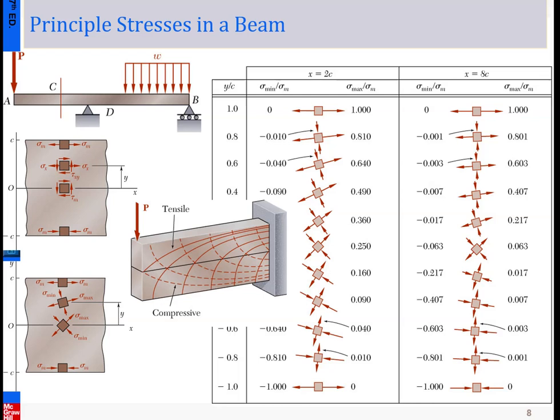We can fit that into the design criteria, and we can justify throughout the whole structure what the maximum stress really is. If we can ensure such a maximum stress is lower than or equal to the allowable stress, then the whole structure will be safe in terms of the design. So again, we come back to our original design criteria. We simply want to make sure the structure is structurally safe.